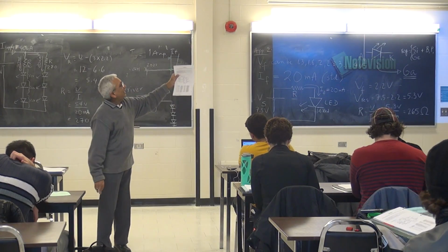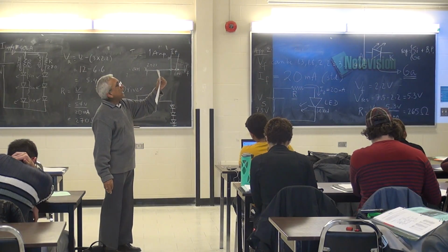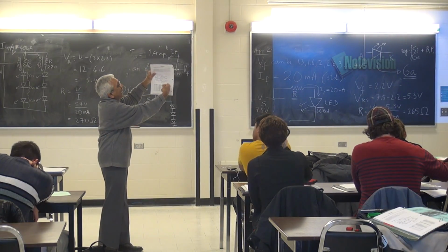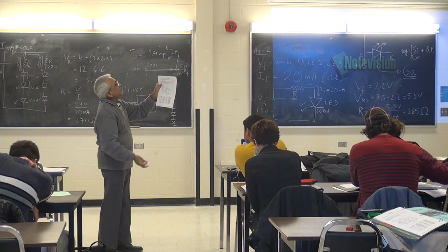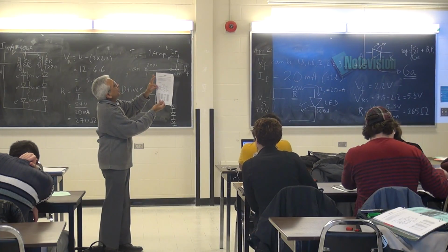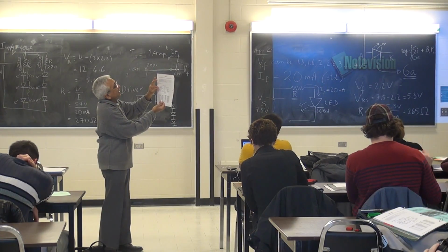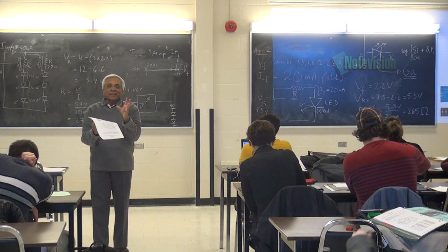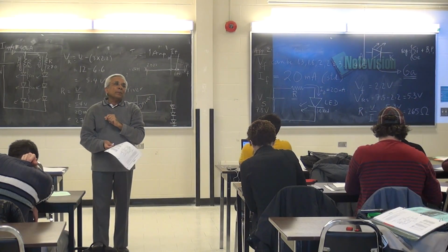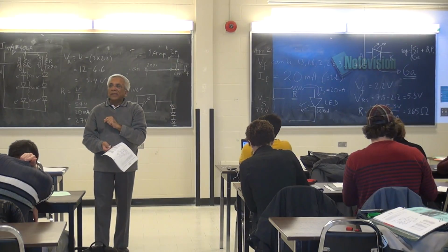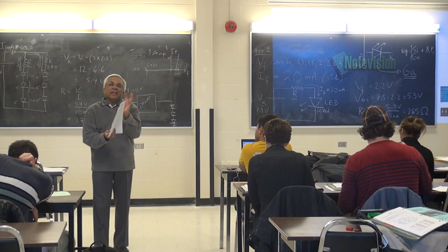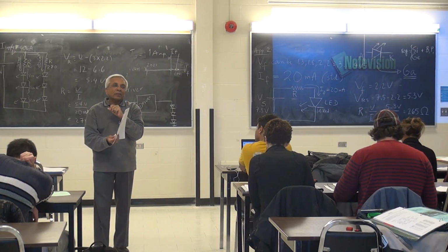So that's what this circuit shows. It's a driver circuit for the LEDs that are shown on the right side. Okay? So you've got a 3409, you've got a bunch of resistors, capacitors, a Zener diode, and that makes up the circuit to operate an LED, a string of LED lights. And then this in turn is connected to an Arduino kind of a circuit, a microcontroller.